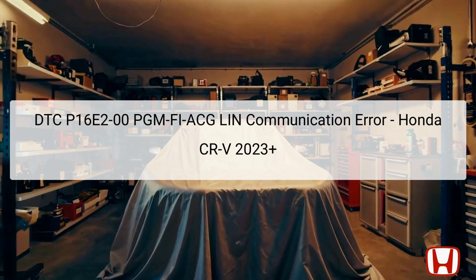The LIN is a communication protocol used to transmit information between various components in the vehicle. The error indicates that the PCM cannot receive expected signals from the alternator, hence it registers the error code. This condition may arise if there is a loose connection at the alternator's positive battery terminal, plus B, which is responsible for providing power to the alternator. It's essential to address this issue promptly, as it could lead to electrical system failures or battery drain.